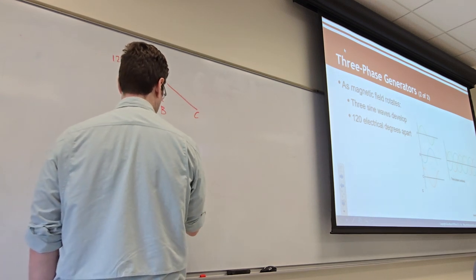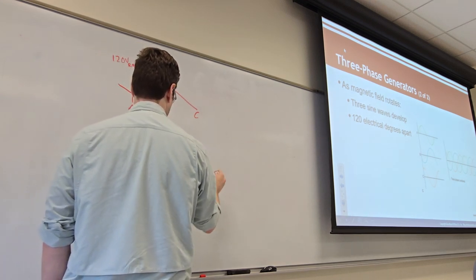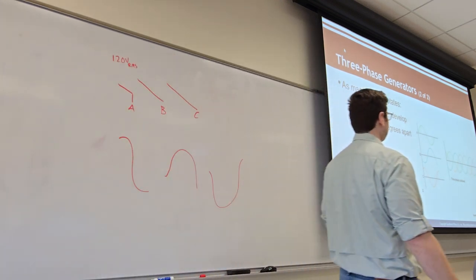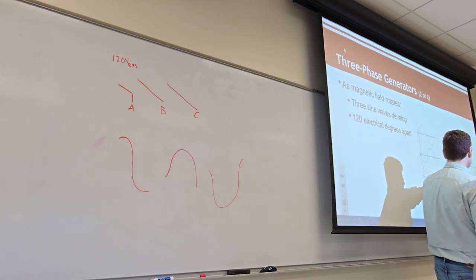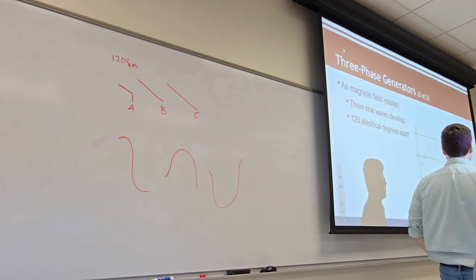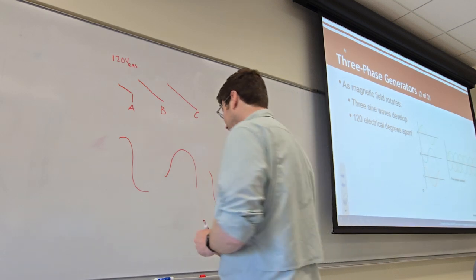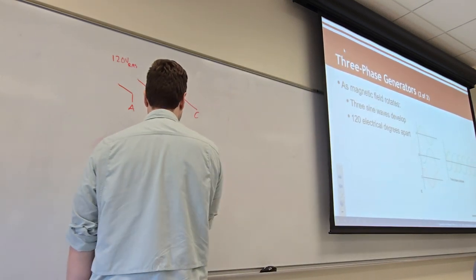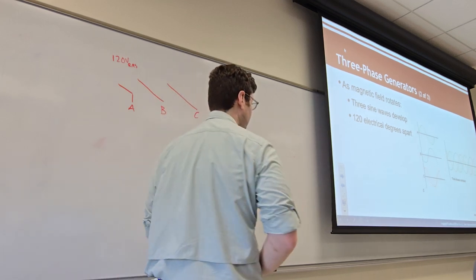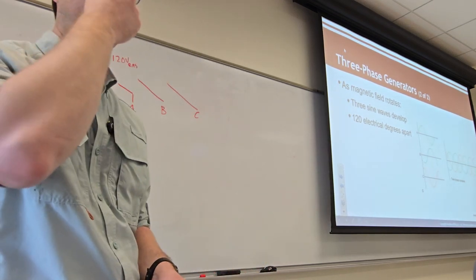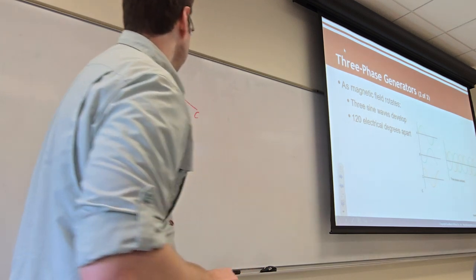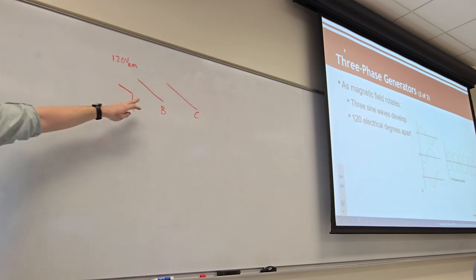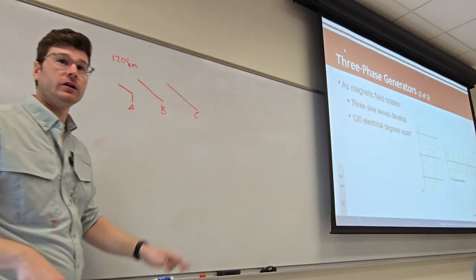This one is up, this one is already on the come up, and this one is maybe going down, just like they have here. There's just the timing is slightly different, forwards or backwards. And it's made that way by the power company. Something is generating these sinusoidal waveforms that are slightly out of alignment in this way on purpose, in our three-phase power. This is the stuff that's coming off of the telephone pole. When you see the three lines coming into a building from the distributor, very often it's for our three-phase power, for our big stuff.